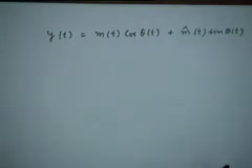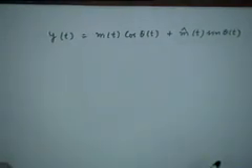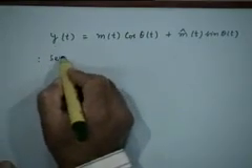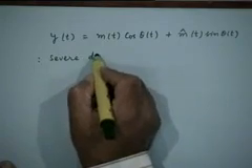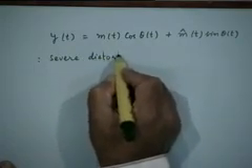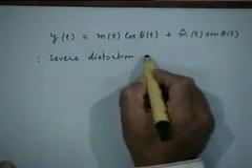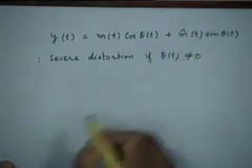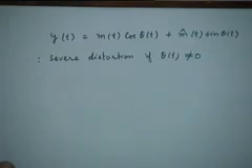So unless theta(t) is 0, this would lead to severe distortion in the recovered message signal. So this is one small problem that we faced in the demodulation process in this case. Of course, if there is perfect synchronization, there is no problem.